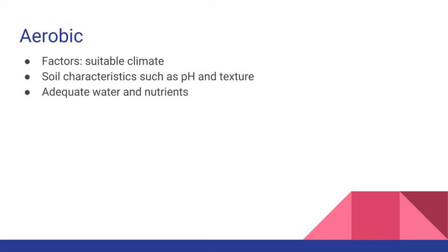Biological remediation, in addition, cannot degrade inorganic contaminants. It is used to change the valence state of the inorganics and cause adsorption, immobilization on soil particulates, and precipitation, uptake, and accumulation of the contaminants in micro or macro scale organisms. These technologies, while still largely experimental, are considered to show promise in the area of biological remediation.